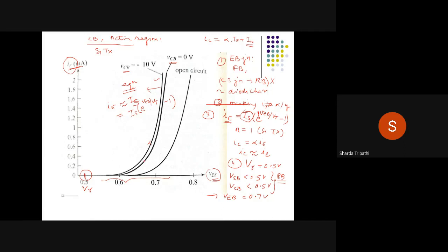So while the current is increasing, there is some voltage drop, but it does not exceed beyond a certain value. This entire region is approximated by considering that whenever this emitter base junction is forward biased, the voltage drop across the junction will be 0.7 volts. So when we are solving the questions, this value will always remain fixed, equal to 0.7 volts.